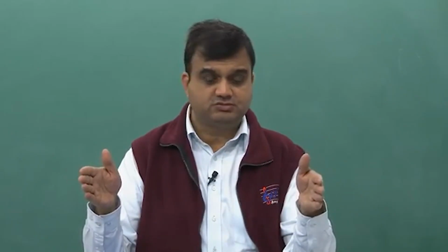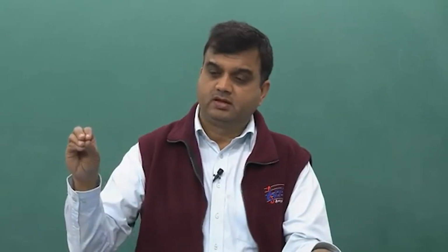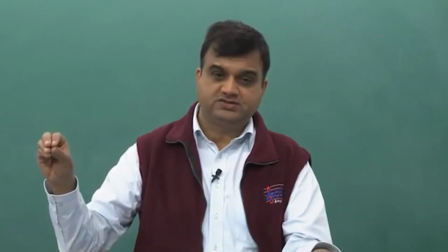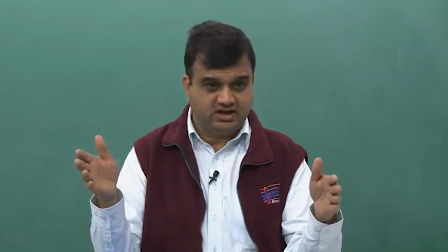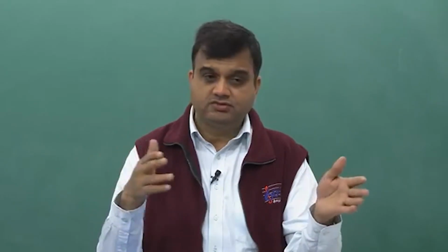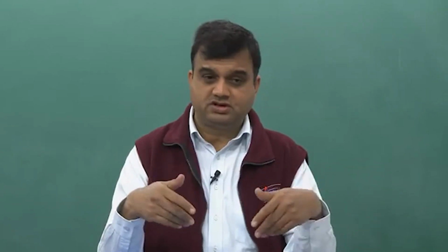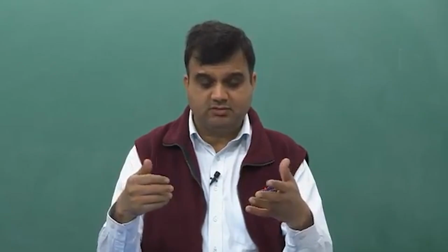So, let us say partial derivative of u with respect to t would be u at time t plus 1 minus u at time t divided by delta t. So, we use in a lot of cases, not always necessarily, a finite difference approach to discretize time, and we use finite element approach to discretize space, and we combine these two and solve time related problems.